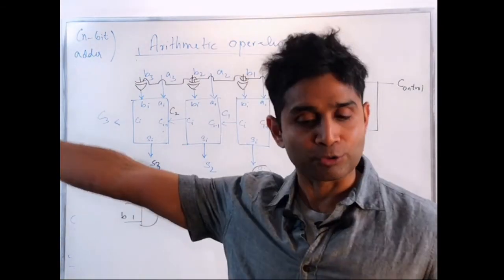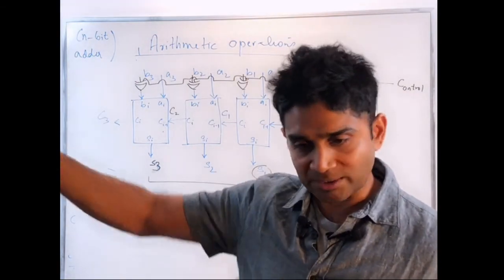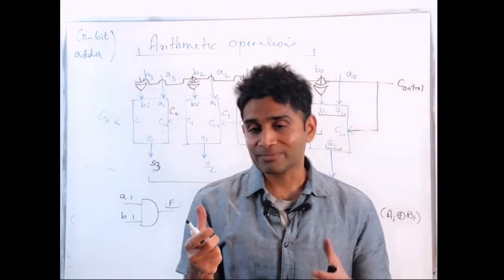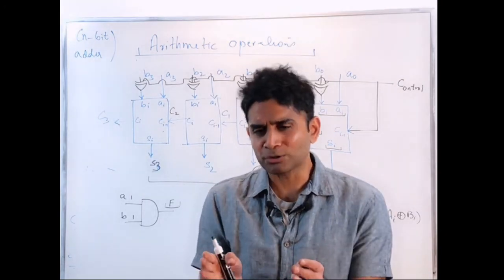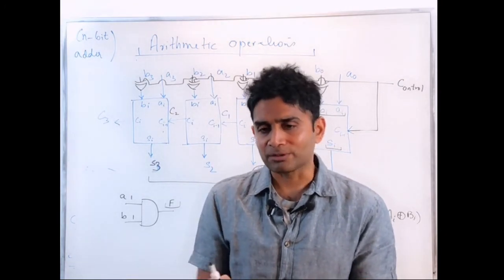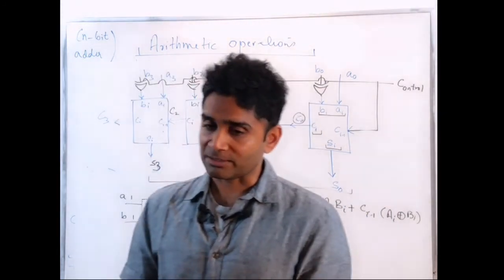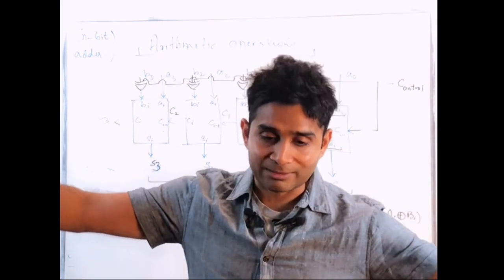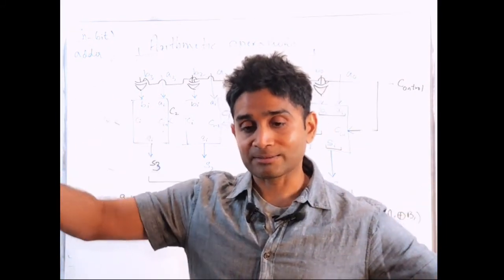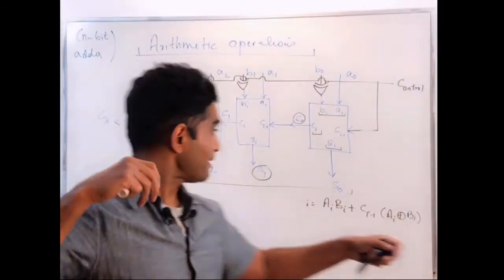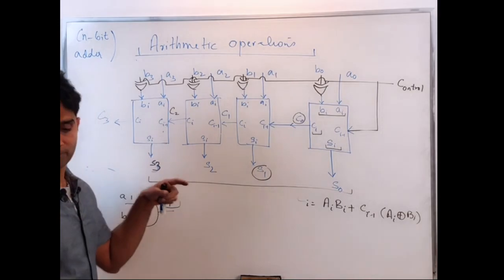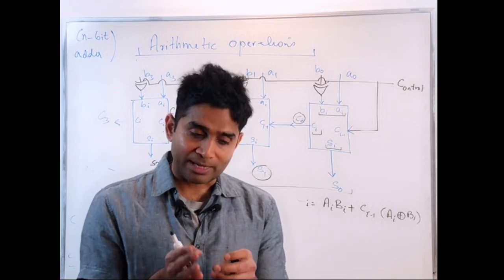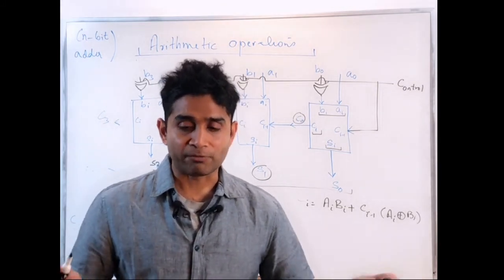And if I add too many modules, the delays just keep getting added up, and it will be a delay that you can actually sense. For small modules, not so much of a problem, because the propagation delay is not much. But if I extend it to a very large module, like 64-bit or maybe 128-bit, then these propagation delays add up, and whatever answer you're getting here, you need to wait. Of course, it will work, but you have to wait a longer time for the sums to settle down, giving you a final correct sum.